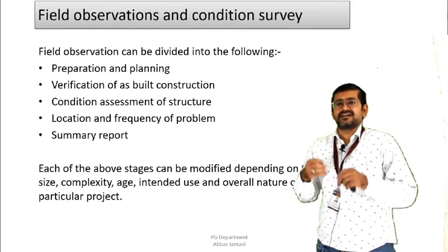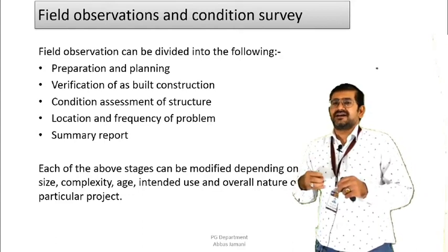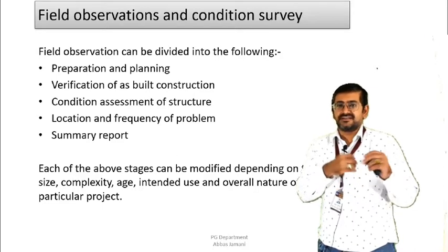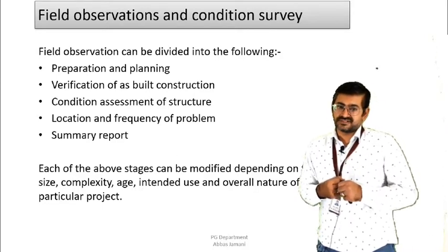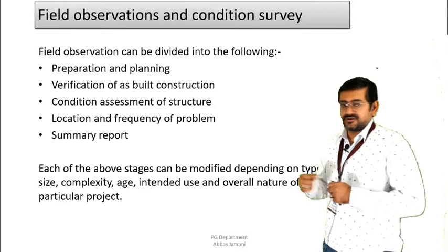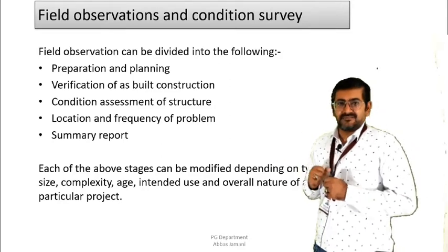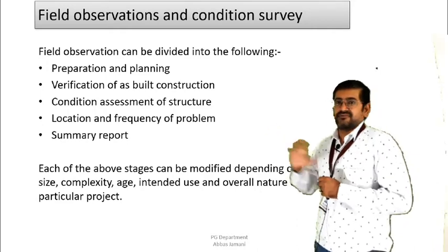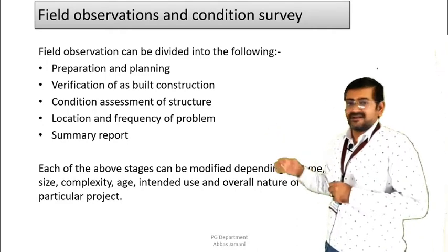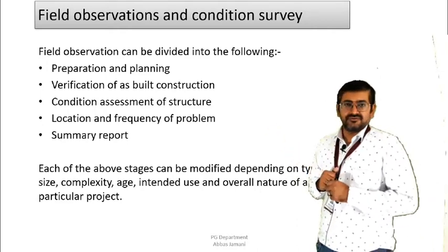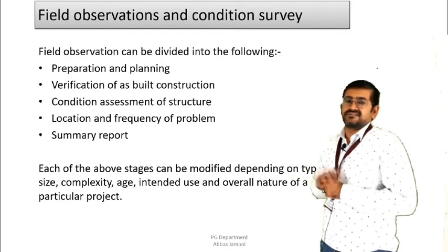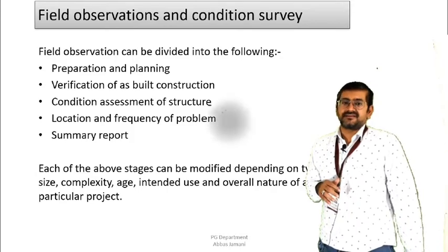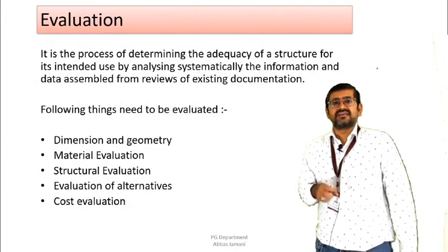And then after collecting all the data, you analyze the data and you decide whether this particular thing is going to have a serious threat to the life of the structure or the performance of the structure or not, right? So first you need to do the preparation and planning at the office level. Then when you go to the site, you do the verification with the documentation data that you have. Then you do the condition assessment of the structure, right? Then location and frequency of the problem, and lastly the summary report based on the observations that you are making on the site.